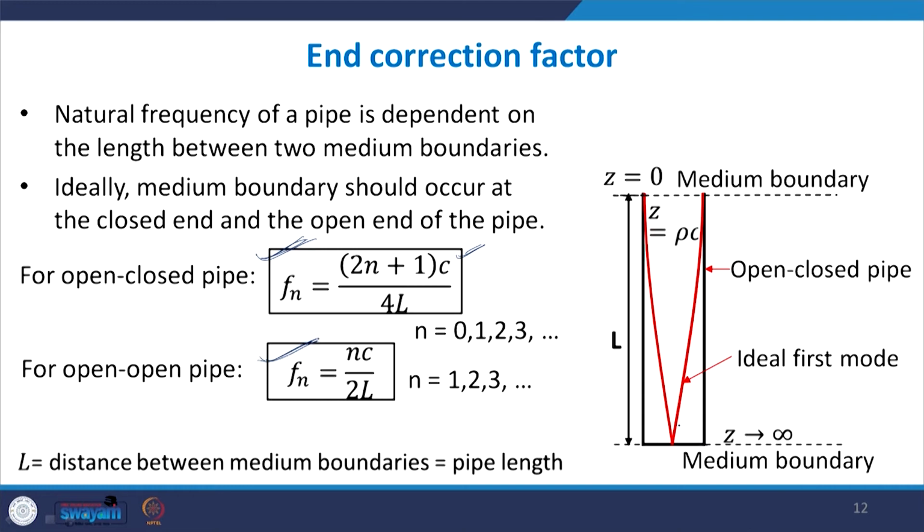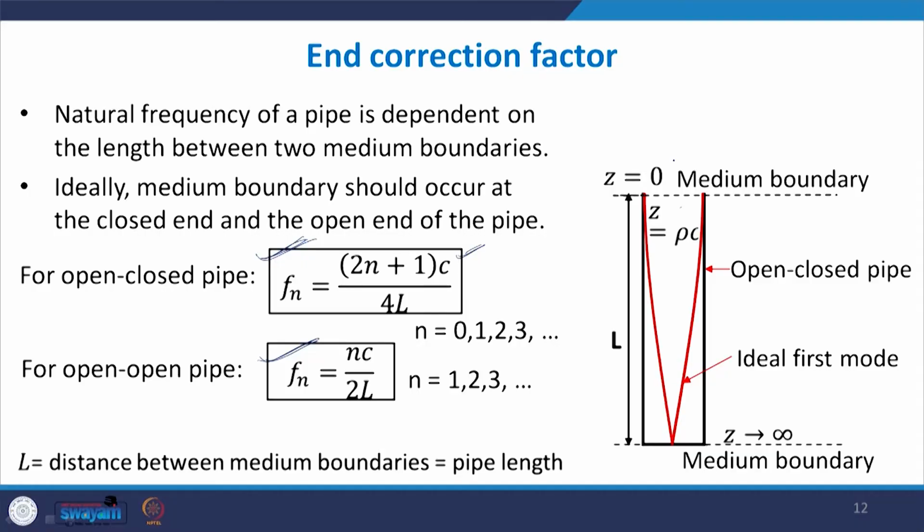When we derived the expression for natural frequency of this particular long tube or pipe, we assumed that one end had almost infinite impedance, and at the other end the impedance is suddenly 0 because it offers no resistance. Here also it is air, and therefore in that case P was said to be 0. So, V equals 0 for the rigid backing and P equals 0 for the open end. Using these conditions we derived the resonance frequency for both the tubes.